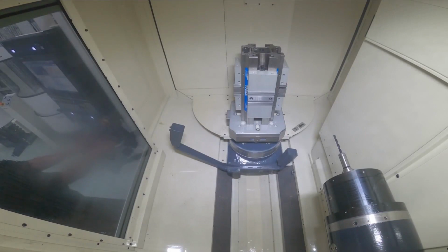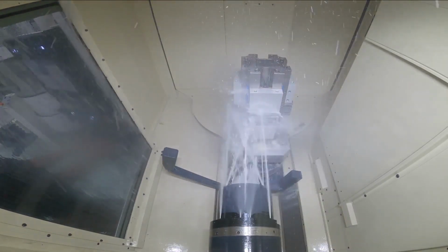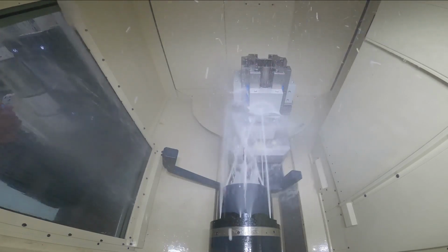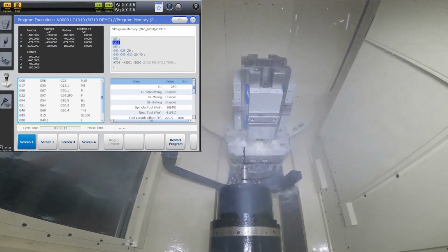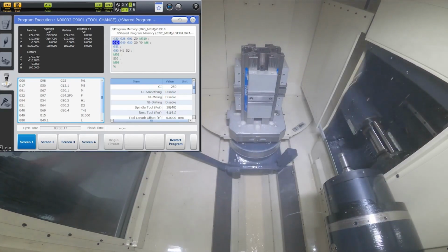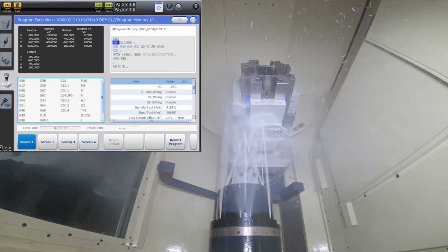Start up, recording the time. And again, this is the serial process where everything is sequential. So spindle stop, orient, coolant off, move over, ATC door open, and tool change. This next one now is implementing the M319, where you do all those steps in parallel.